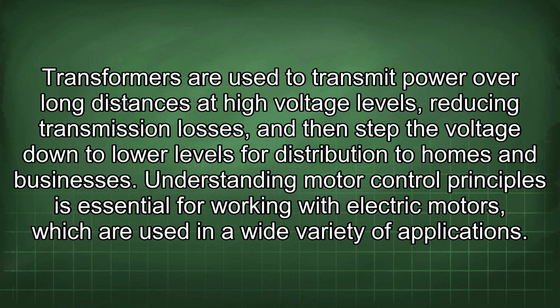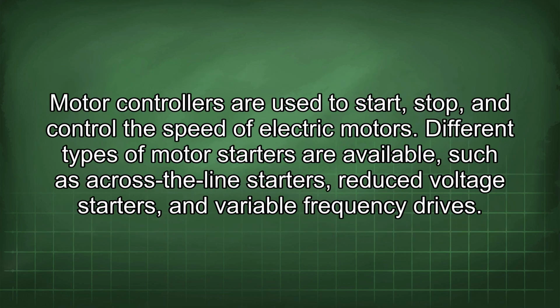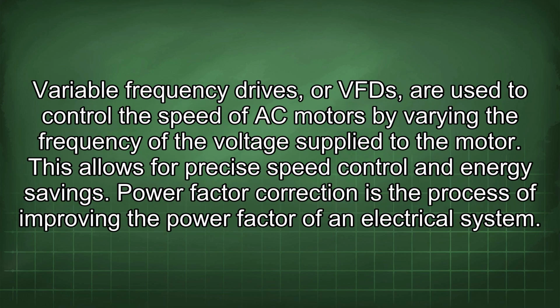Understanding motor control principles is essential for working with electric motors, which are used in a wide variety of applications. Motor controllers are used to start, stop, and control the speed of electric motors. Different types of motor starters are available, such as across-the-line starters, reduced voltage starters, and variable frequency drives. Variable frequency drives, or VFDs, are used to control the speed of AC motors by varying the frequency of the voltage supplied to the motor. This allows for precise speed control and energy savings.